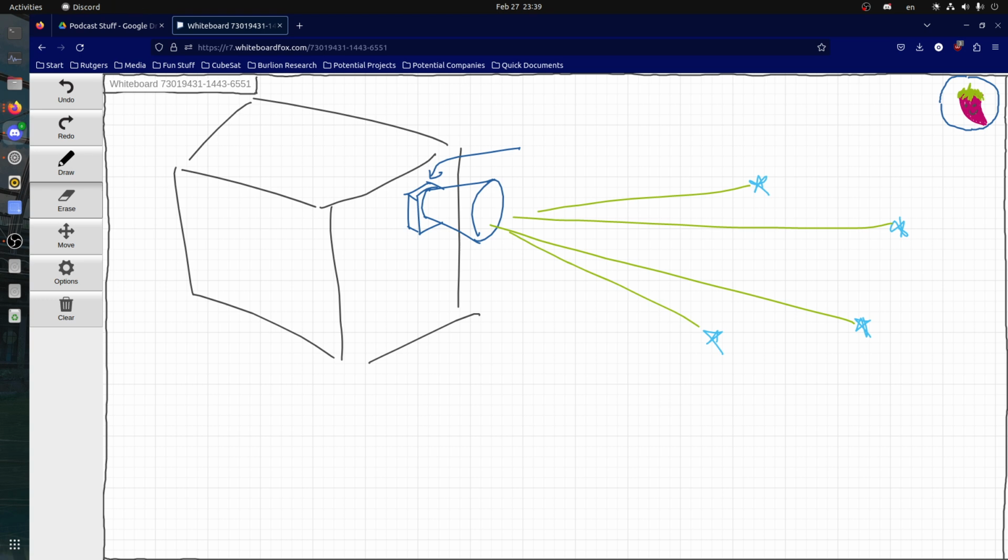One thing to note though, even though these things work pretty fast, which is like 1 to 2 hertz, well, I consider it fast, they're not as fast as a control algorithm is. Usually the star trackers are at less than 10 hertz, so I'll just use 10 hertz.